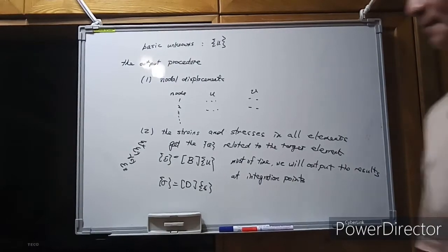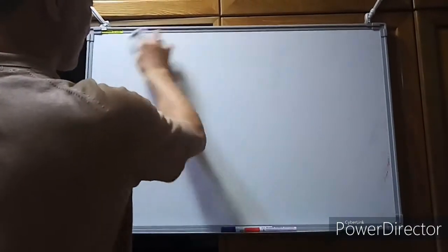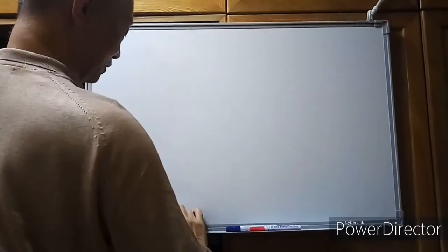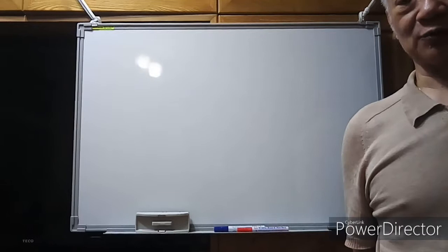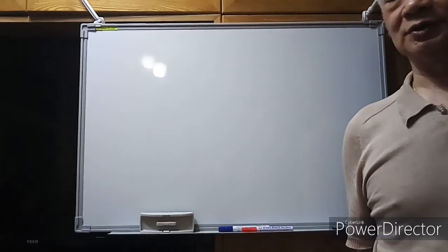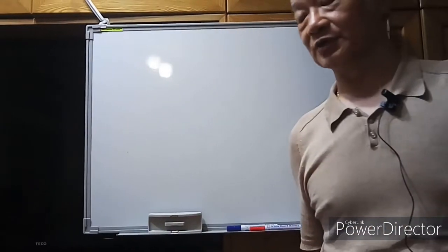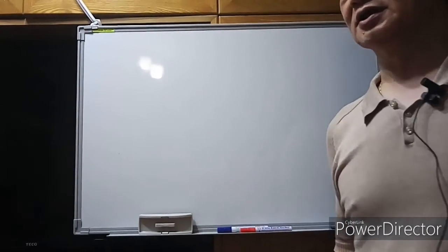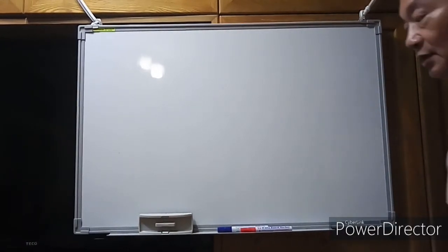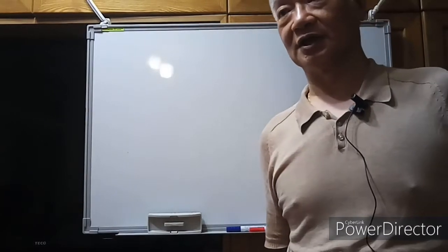Then I will continue. Okay, I have finished all the things I would like to tell you about the plane strain problems, and that's the only element and the only problem for which I will give very detailed discussions: how to calculate a small K matrix, how to assemble the global K matrix, how to calculate the load vector for elements, and how to assemble those local load vectors into the global load vector.